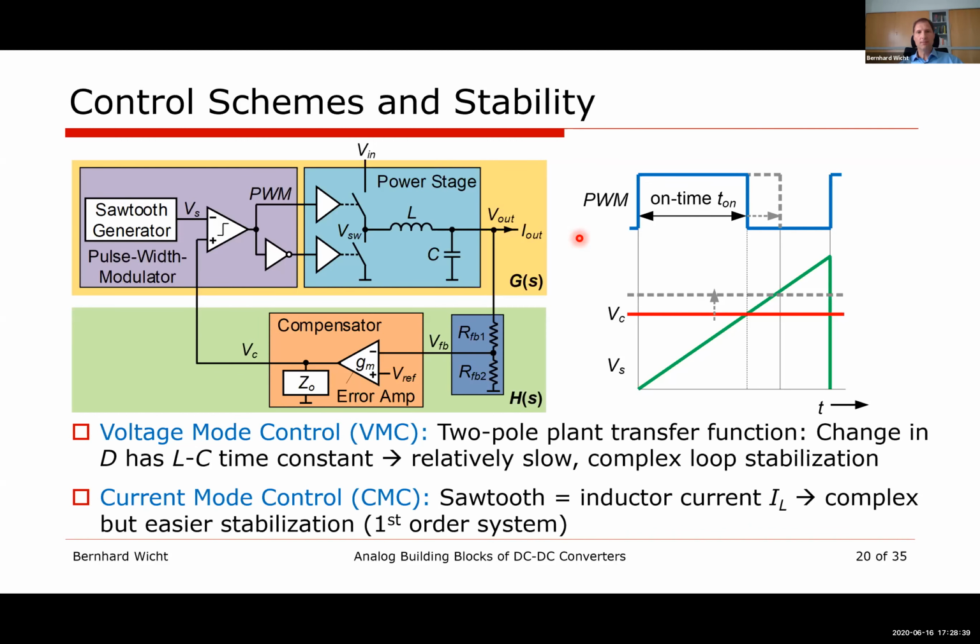Yeah, there are some controllers on the market that are really ultra low power. They usually try to get the power down by reducing the switching activity. What they do is they go from pulse width modulation into pulse frequency modulation, sometimes called burst mode, which allows to turn off most of the components. What they leave in is a comparator that observes the output voltage.